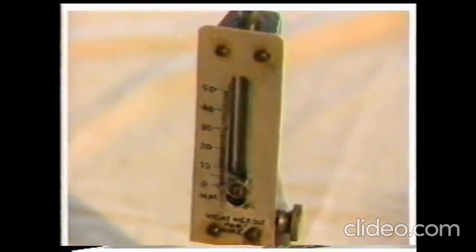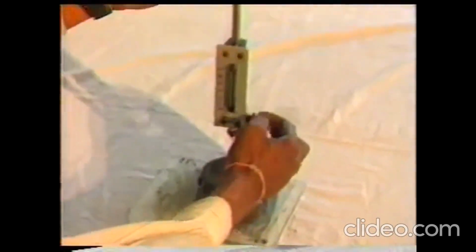Fill the Vicat's mold with the cement paste so prepared and level the surface. Place the test block under the needle. Lower the needle till it comes in contact with the surface of the test block and gently release, allowing it to penetrate into the test block and observe penetration. Repeat this step at appropriate time till the needle fails to pierce the test block 5 to 7 millimeters from the bottom of the mold, and note this time.